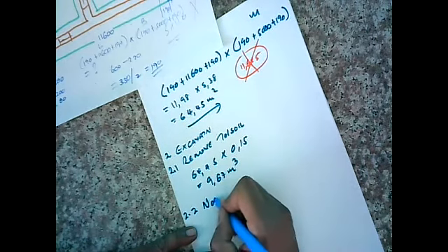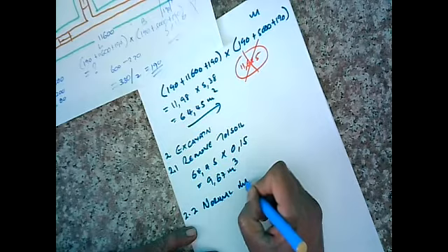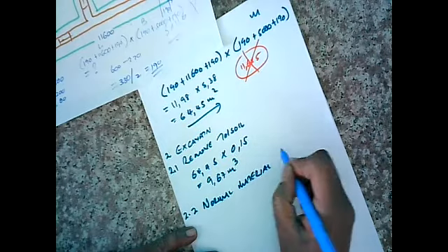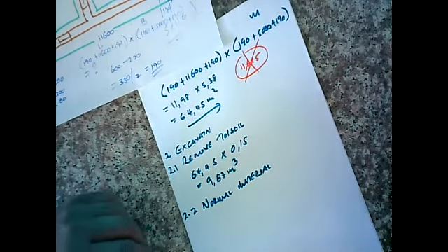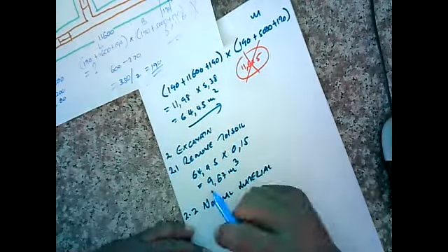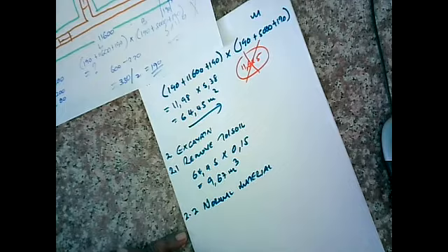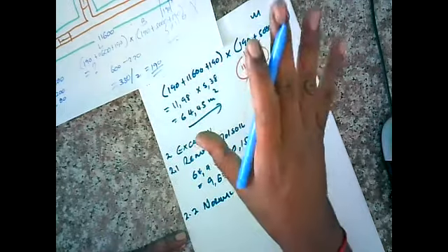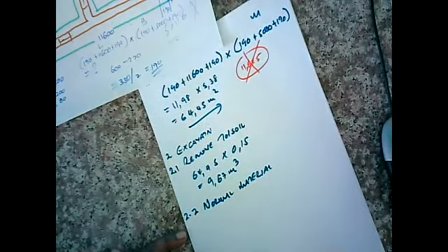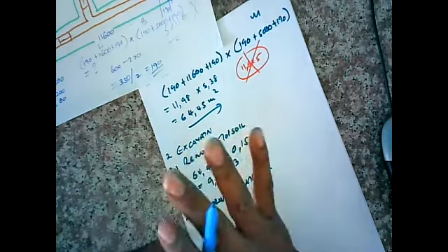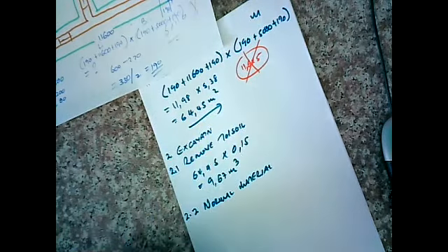All right, normal material. And thankfully, there's no rock or clay or sandy soil in the strata as we excavate, and we don't have to do extra work in terms of the extra over, because the question doesn't tell us rock is found at 450 millimeters below natural ground level. So we just assume everything is normal, everything is good. Now, what are we finding normal material?